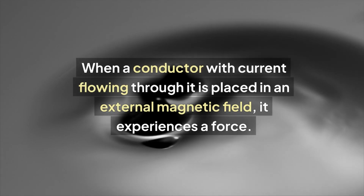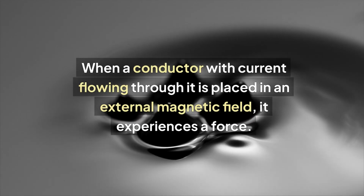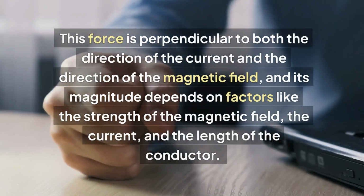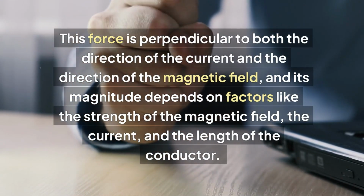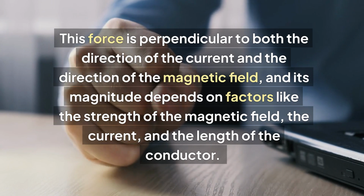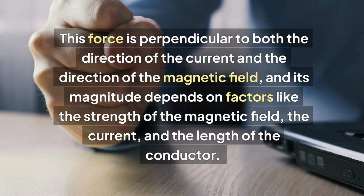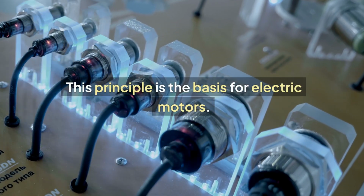Next, we must understand the force on a current-carrying conductor in a magnetic field. When a conductor with current flowing through it is placed in an external magnetic field, it experiences a force. This force is perpendicular to both the direction of the current and the direction of the magnetic field, and its magnitude depends on factors like the strength of the magnetic field, the current, and the length of the conductor. This principle is the basis for electric motors.